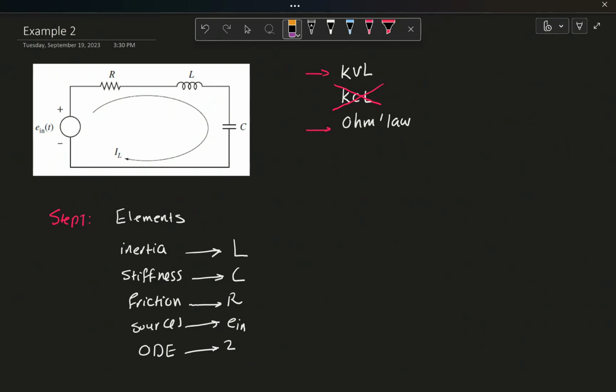Okay. Now, let's go ahead and walk on this circuit in the direction of the current that's shown to us, in this direction. And I'm going to work with the direction of current IL that was assumed and given to me. Yes? Okay. If I move in the direction shown, which is the direction of the current, do you guys agree that the voltage across the resistor drops because I'm moving in the same direction of the current?